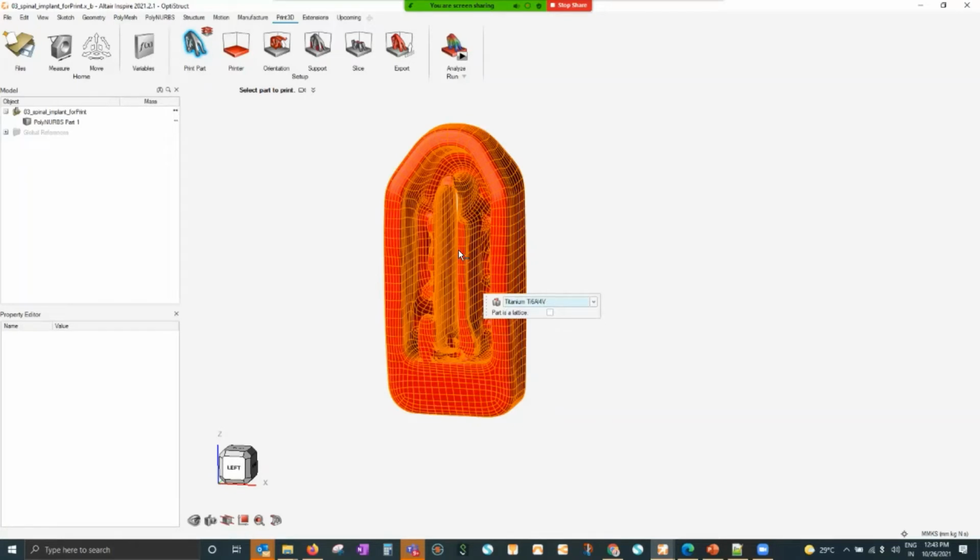And if the part has a lattice structure, make sure you switch this on, because then the meshing treatment will be different. But here we don't have a lattice. We'll see an example on lattice as well, not for printing, but how to create a lattice, later on. So this material part is done, and then you can right click and come out of this window.